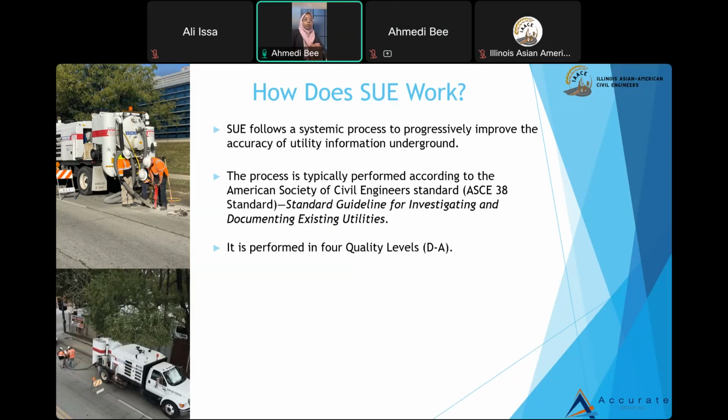The quality level goes from D to A, D being the lowest level of utility investigation and A being the highest. And SUE is not just a typical process, it's actually an ASCE standard. We follow ASCE 38-22, a standard guideline for investigating utilities.